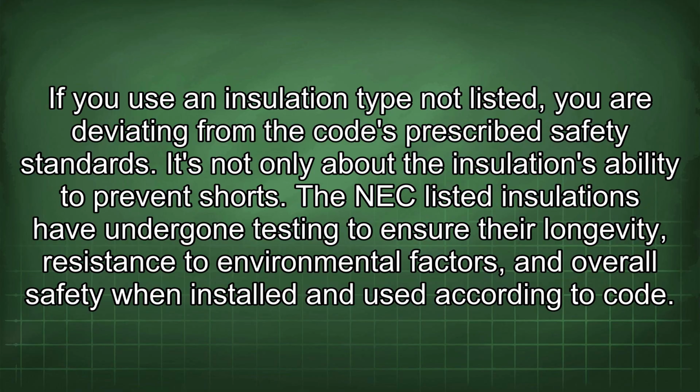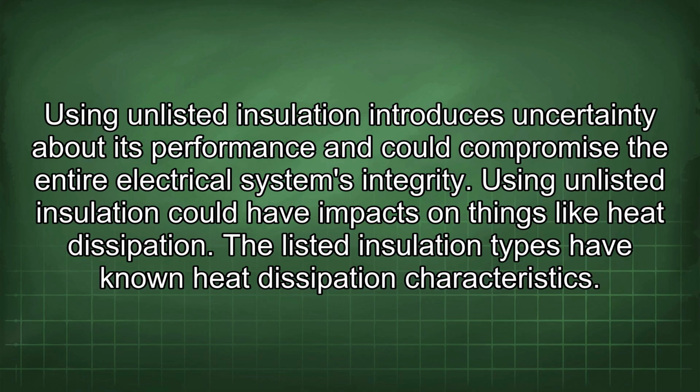It's not only about the insulation's ability to prevent shorts. The NEC listed insulations have undergone testing to ensure their longevity, resistance to environmental factors, and overall safety when installed and used according to code. Using unlisted insulation introduces uncertainty about its performance and could compromise the entire electrical system's integrity.